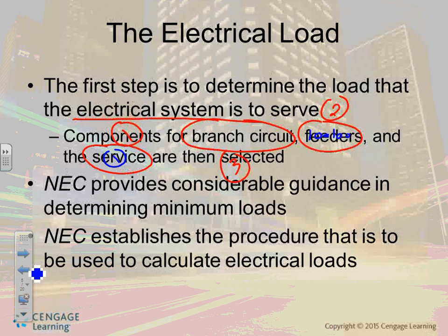And remember, they call some branch circuits feeders, so be very careful of the term. A feeder is between two panels. A conductor going to the air handling unit is not a feeder, even though a lot of engineers call it a feeder, guys, right? Size the feeders; they are branch circuits. So you can't mix them together.